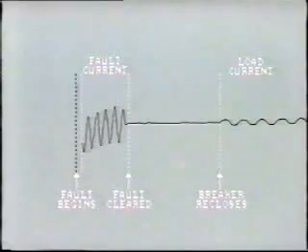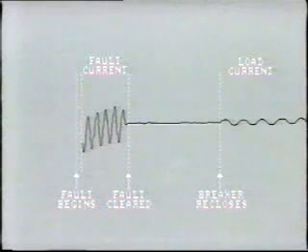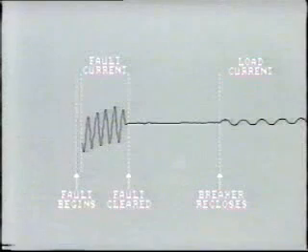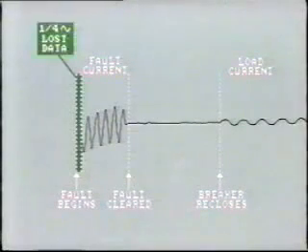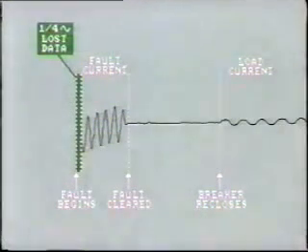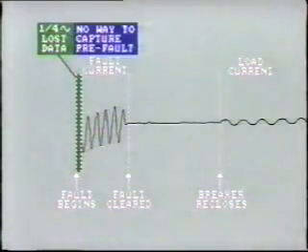As soon as a fault is sensed by a protective relay or other sensor, the machine starts and the paper begins to move after 3 or 4 milliseconds. Of course, this presents a problem since the data at the very beginning of the fault is lost. The loss amounts to about 1/4 cycle of data. Also, there is no way of capturing the conditions on the system just prior to the fault.